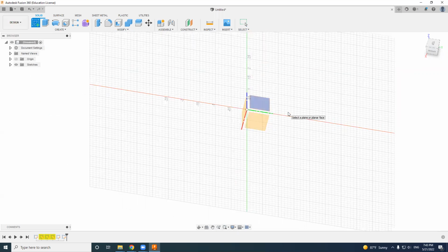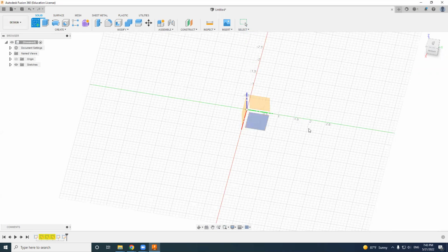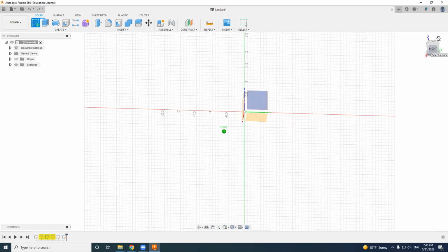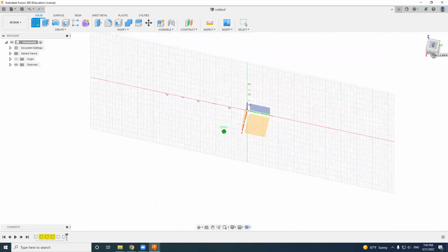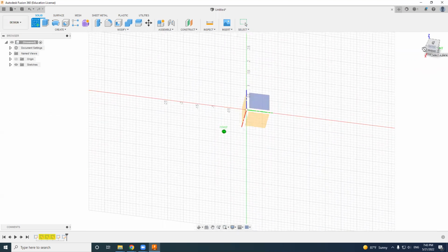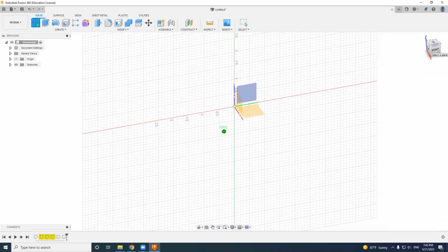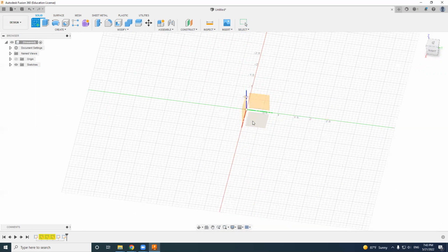If you want to draw a 3D part, we first need to start with a 2D drawing, and then make it a 3D. Then for the 2D drawing, we need to select which plane we want to draw on. And you'll see here, you can find the right, top, and also other planes. And now I would like to choose this plane.